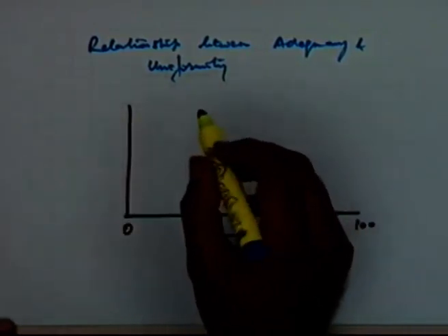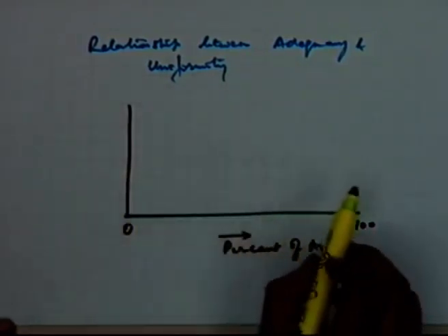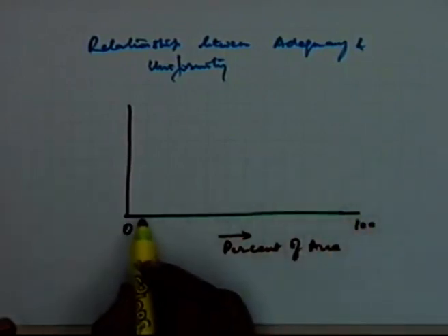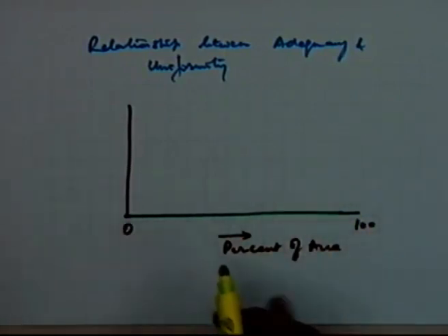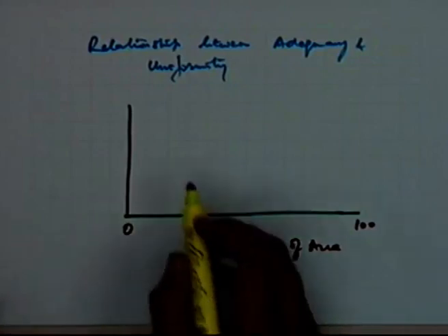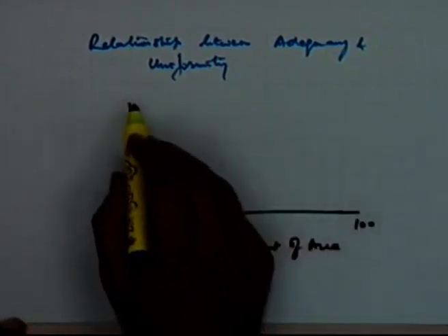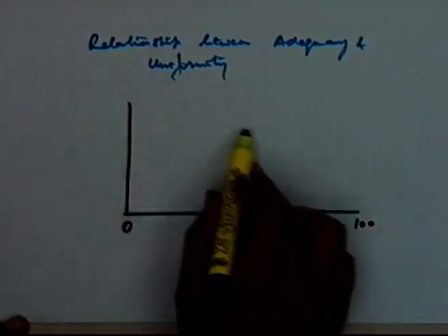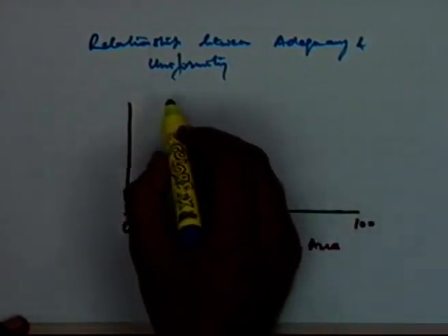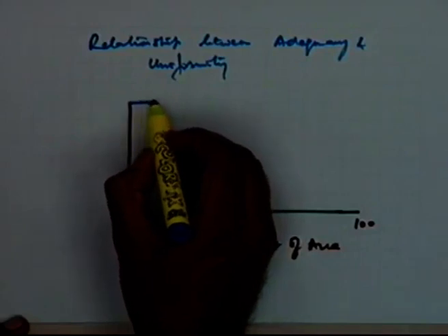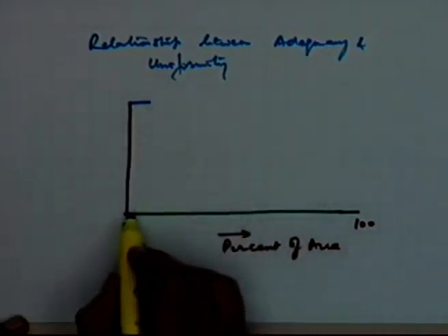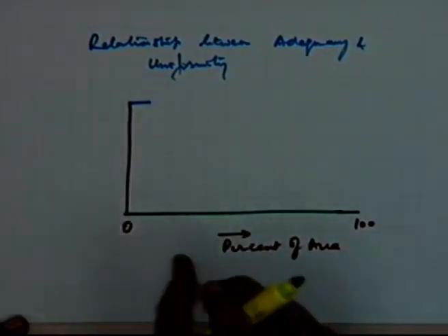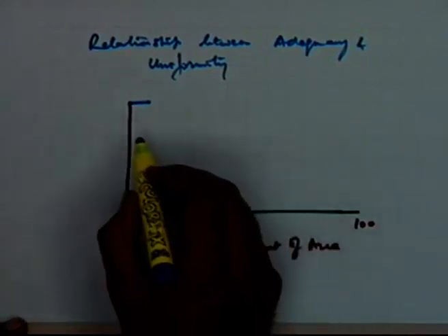And the applied water depth is different. So if we take for every 10% interval, the increment, how much is the average depth, normally you can show it as a continuous line, but you can show it as a bar if you take only 10% of the area at one interval.